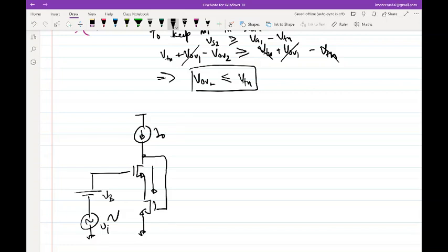There won't be any incremental current, right? There cannot be, because it's a constant current bias. If there is an incremental current, it has to flow somewhere, right? But the VGS is held constant, which means it cannot flow anywhere. If it cannot flow anywhere, it will not have any incremental current. So regardless of whatever you see, nothing will change.